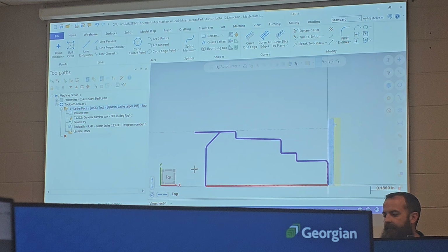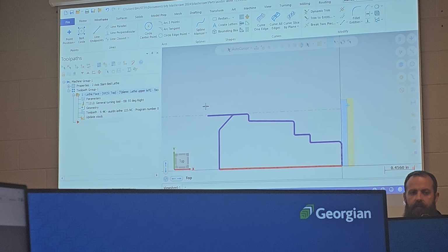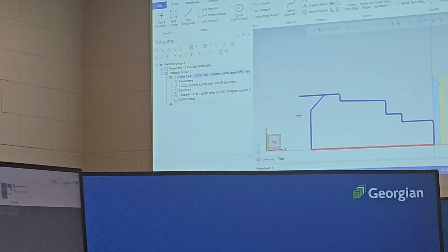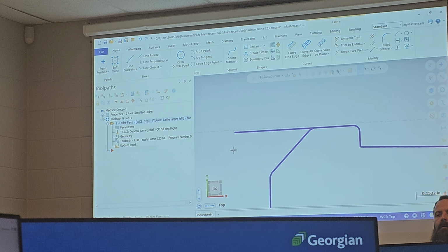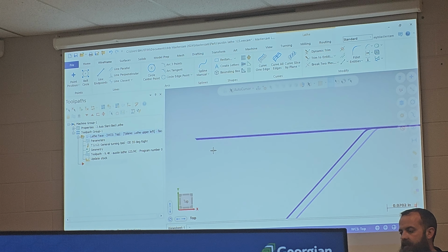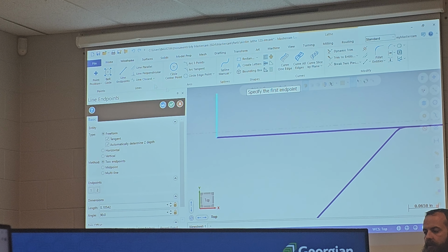The last thing, if this was a large shoulder, like say the diameter of the bar was much larger than 1.75, using a line toolpath right now, it wouldn't know that when I go to rough it. It would only see the diameter expressed by here. So to do this accurately, I actually need a little bit of tail. I'll draw this here like it's a shoulder.